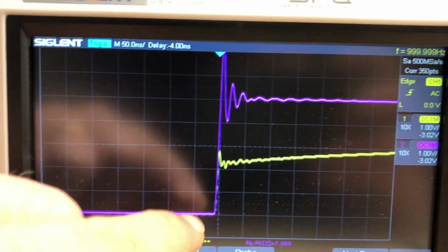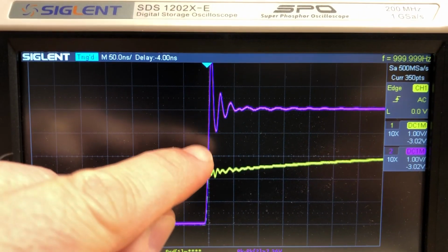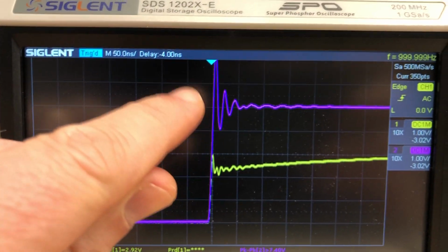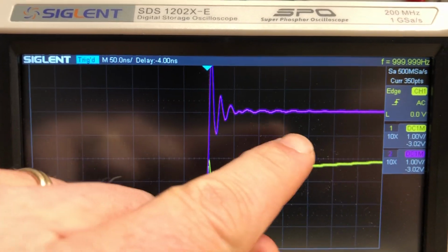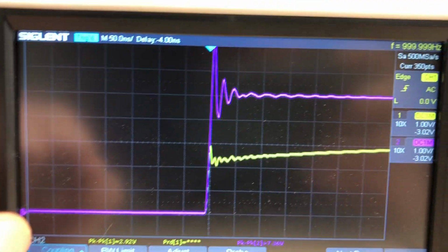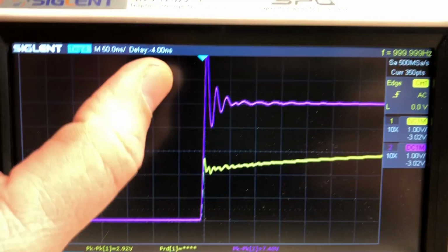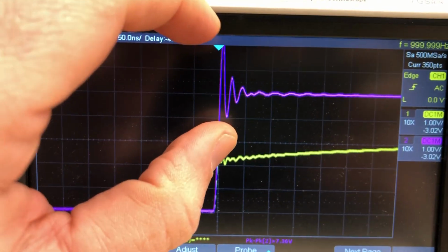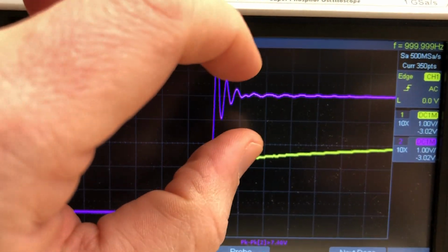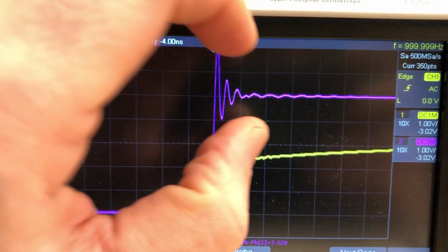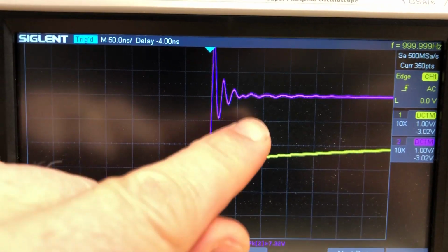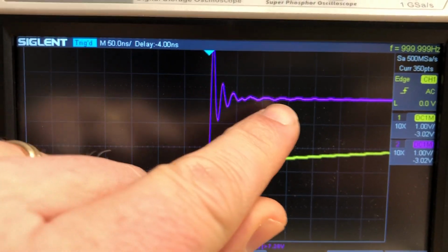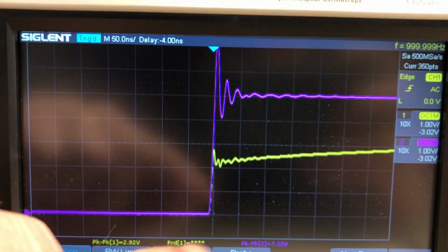So here we can see that we have this big increase. It's pretty good. We get this overshoot and then this decrease, and then it zeroes in on the 5 volts. That's called the ringing. So what we have is the domination initially of the sine wave component, which is then dampened down by the exponential decay of that function. It zeroes in on 5 volts.